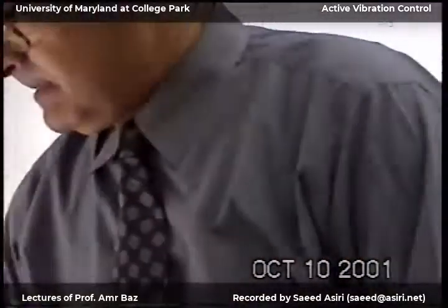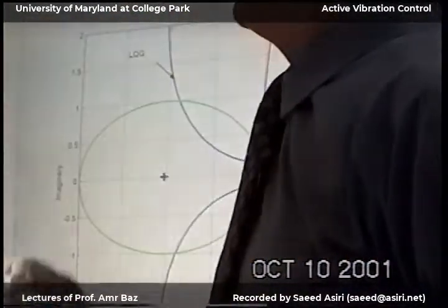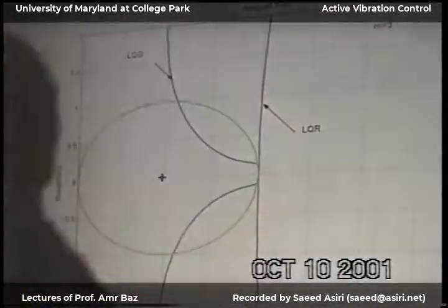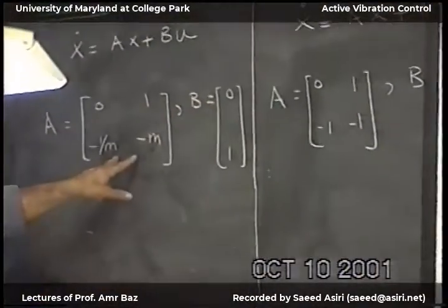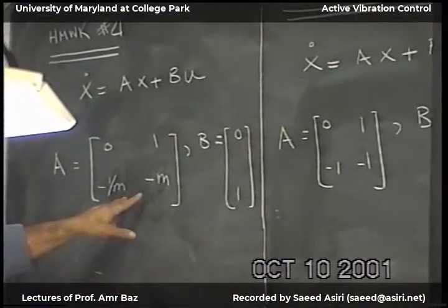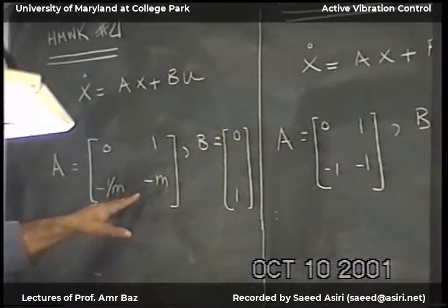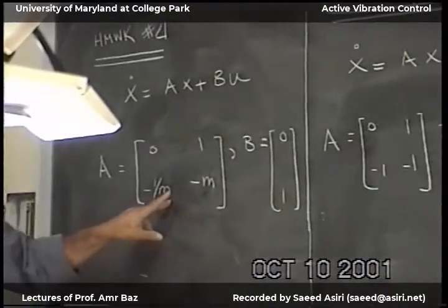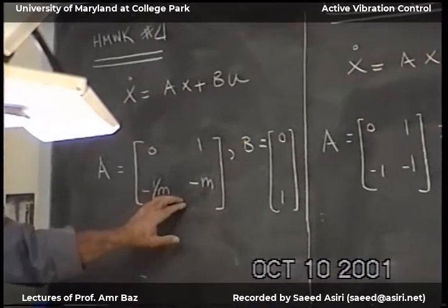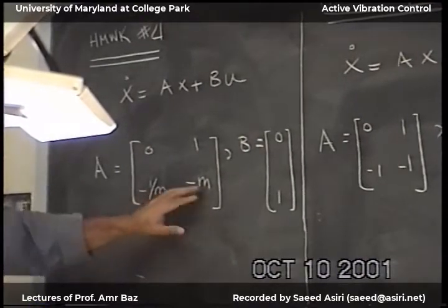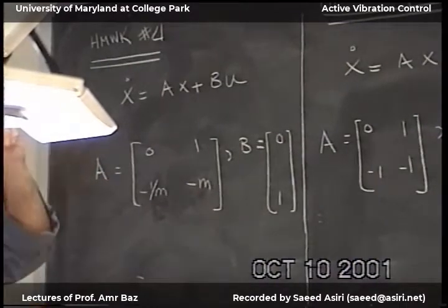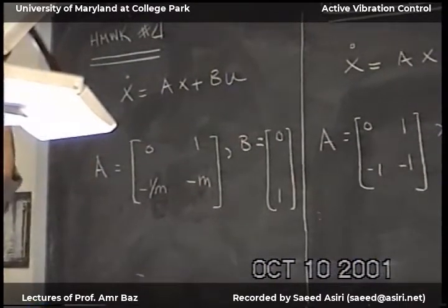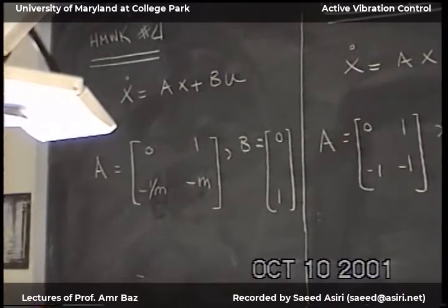Okay. So now, the same applies for the homework problem. All you have to change is the A matrix. You do the gains of the filter and the controller for the nominal system. When you do the state space to transfer function, you have to look at the system that has the uncertainty. Okay? We don't have to plot Nyquist plot. You can also look at Bode plot. And you have the criteria for the stability limits for the Bode plot.